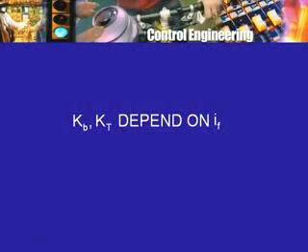So now we will have to do our calculations in a little different manner. We will say that okay, the supply voltage is known to us, let us say it is 230 volts. Now it is a good approximation that the torque constant and the back EMF constant are proportional to the field current. Of course this approximation holds provided the field current is not very large.